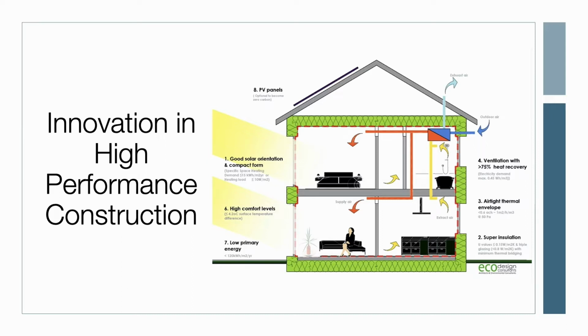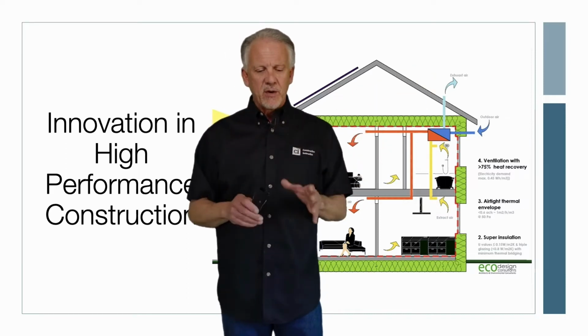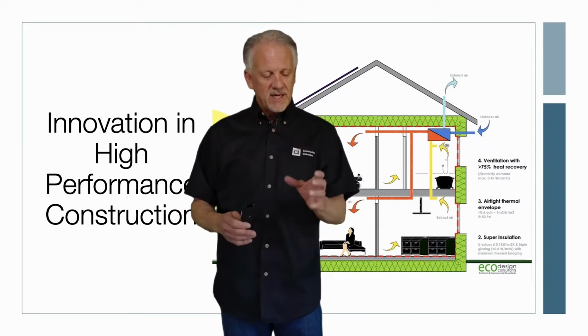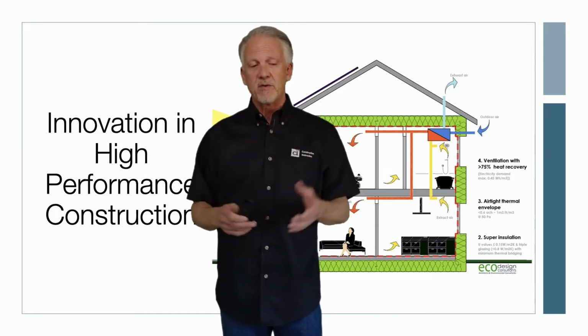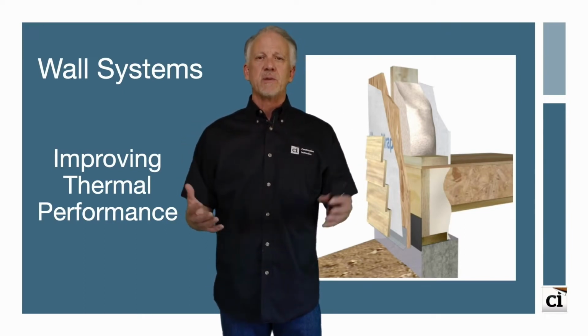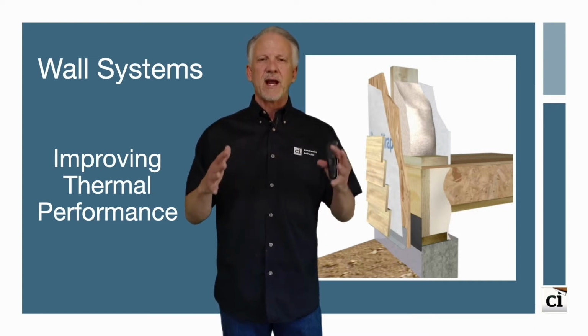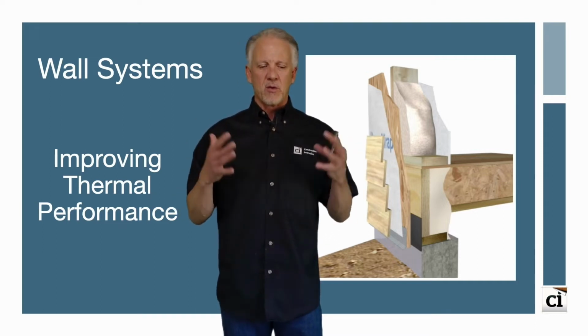With more insulation, there's almost no energy from inside the building driving through to the outside, which also in the past had helped dry wall cavities and assemblies. Now we know that we're getting greater insulation levels in wall cavities as well as even on the exterior of the building. We know that thermal drive is different than it used to be, and that's added to this complexity and added to this challenge of looking at how building performance really affects the overall issues.